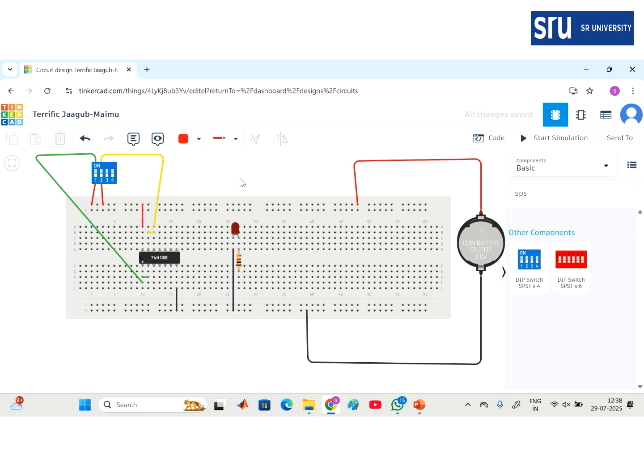Okay, now what is the output available at output 4? Output 4 is B bar, and output 1 is A bar. Alright, now I'm using 2a, 2b, and 2 is my last NAND gate. Now connect this output 1 to 2a. So let us change the color to purple. That is the first input to the third NAND gate. And where is my second input available? At output 4, my second input is available.